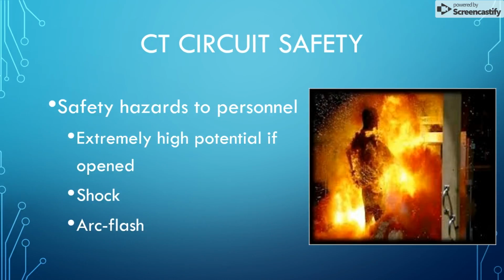It's extremely hazardous to personnel to open circuit a CT. You have an extremely high potential if it's opened. You also run the risk of shock or an arc flash.